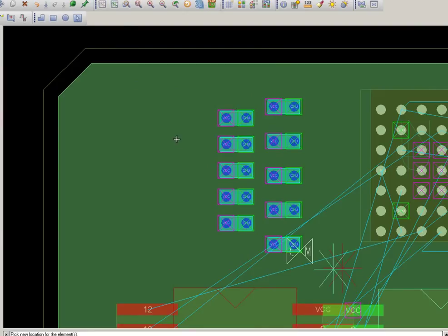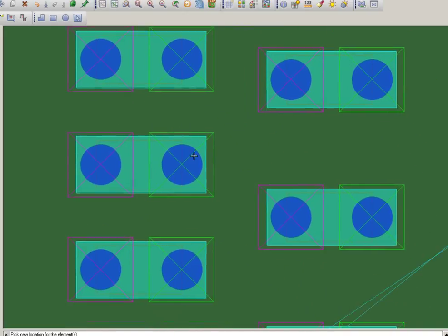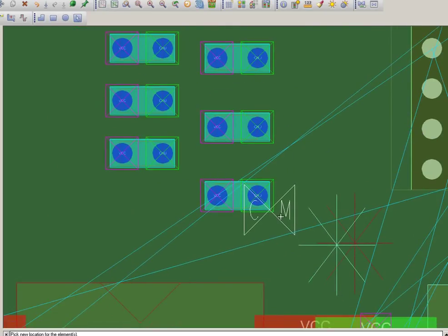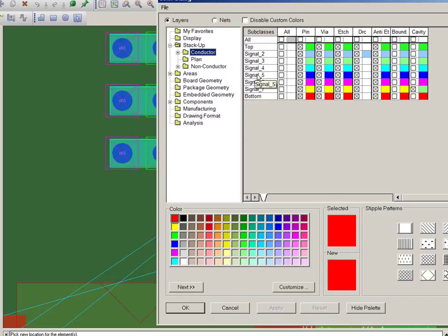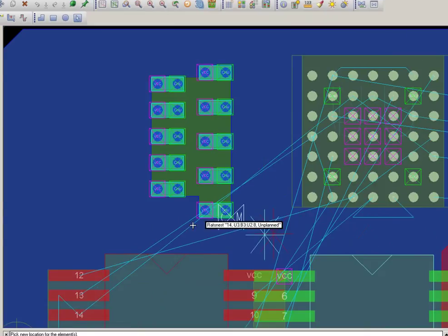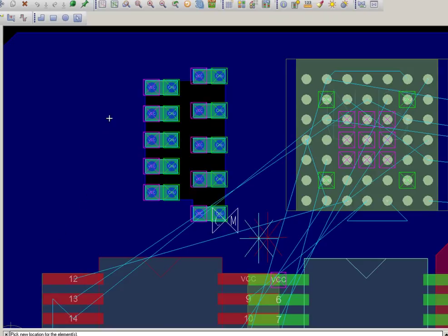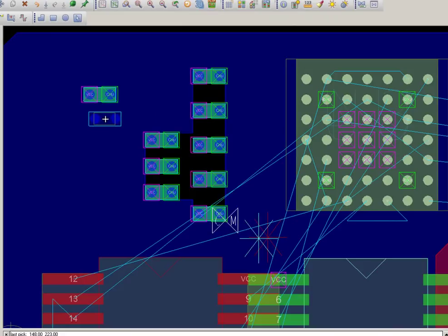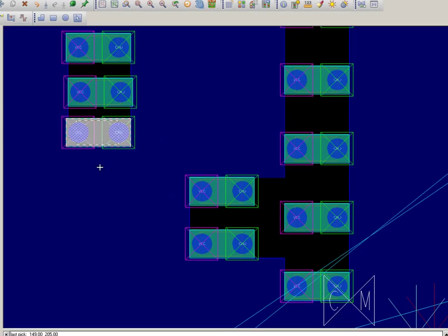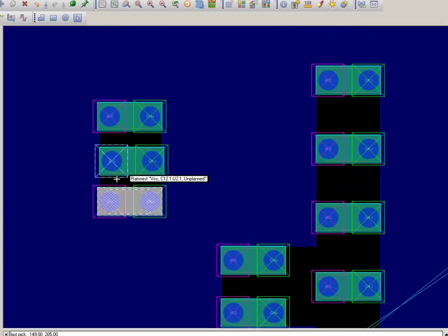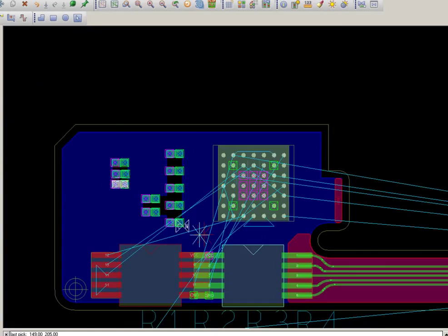The next step, I'll have to turn off the green layer, which is the cavity layer associated with layer 7. I'll go to the color dialog and make the appropriate adjustments there. You see a merger first of the two cavity layers, and now we'll eliminate the green layer. Moving components to the left to illustrate the dynamic merging of cavities when these components are below 20 mils. With that setting that we said earlier, the cavities will dynamically merge.